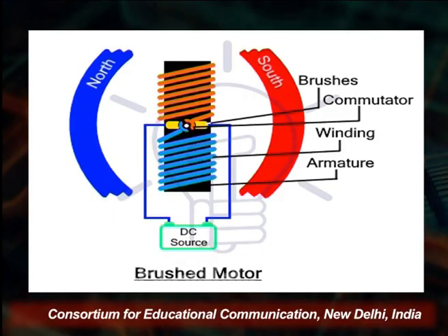Conductive brushes play a very important role in the rotation. The disadvantage of this type of motor is that it requires frequent maintenance due to continuous sliding of the brushes and the spark generated between them. However, they are quite simple in design and inexpensive.